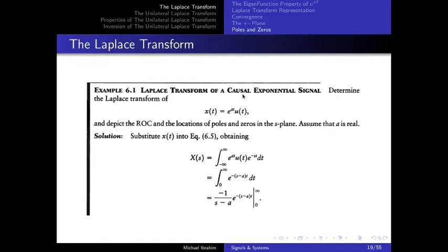The idea is that if this signal is the impulse response of an LTI system, this LTI system would be causal, because x of t over here is multiplied by u of t, so it's basically 0 before t equal to 0. That's why it's considered to be a causal signal. But again, causality is a description of a system rather than a signal.